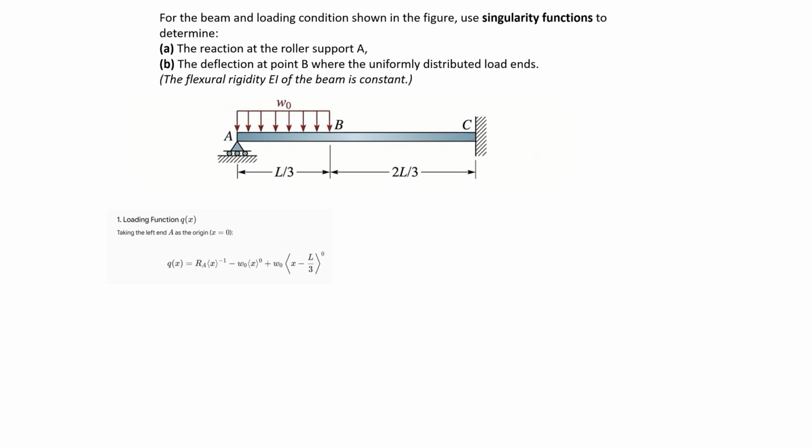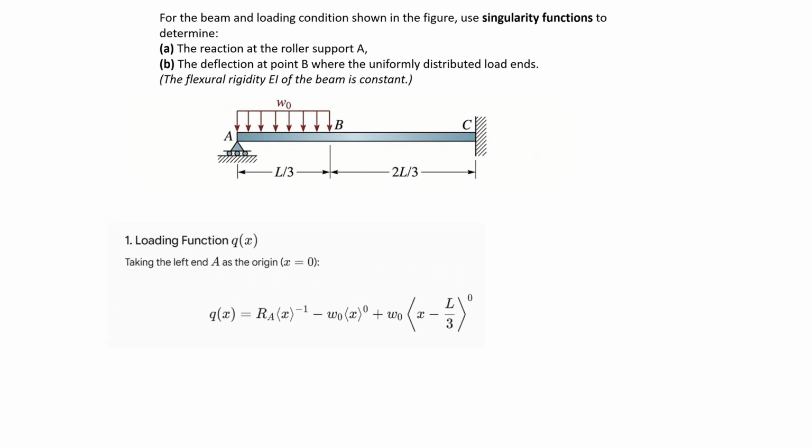Let's do a quick refresher on the golden rule here. How do the exponents change when loads enter our equation? For point loads, our exponent is always -1. For rectangular distributed loads, it's 0. And if we had a triangular load, it would be 1, along with its slope coefficient. Looking at our problem, we only have a point load and a rectangular load, so we're chilling.